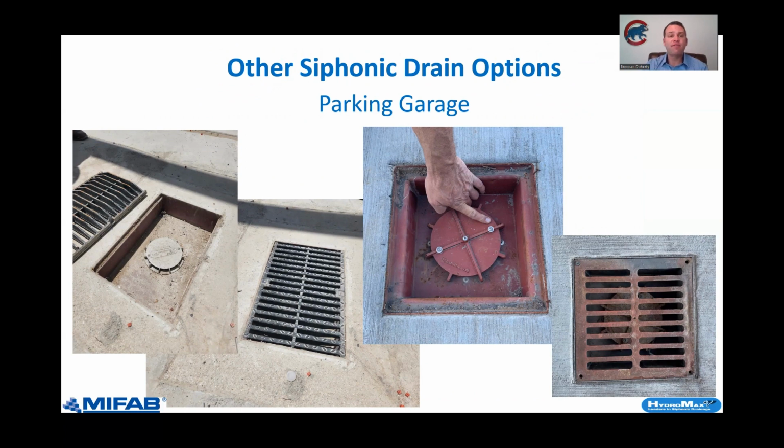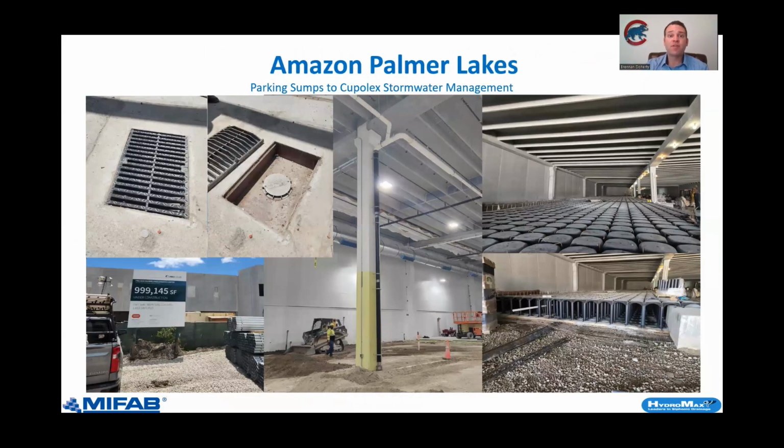Other option we have for siphonic drains is putting one in a parking sump. We also offer trench drains, so it's a standard grate. Working with Amazon on one of their projects down in Florida, the benefit for them here was we could collect more drains together, which means we had less vertical shafts.